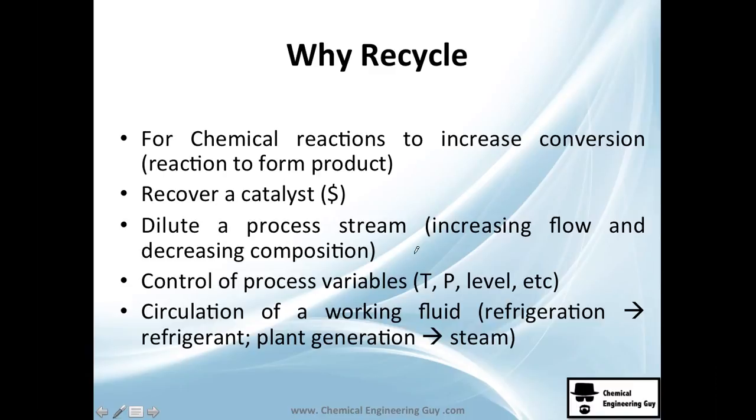Now, the obvious question is why recycle? I mean, chemical process recycle. Now, the important thing, we're not seeing this right now, but for chemical reactions to increase conversion, you need to recycle. So if you have a conversion XA of, I don't know, 10%, if you simply recycle that, maybe it will react to 20%, who knows? So that's why they do it. Sometimes they need to recover a catalyst, which means money, because catalysts in general are expensive. So they prefer to recycle and reuse it rather than just throw it away.